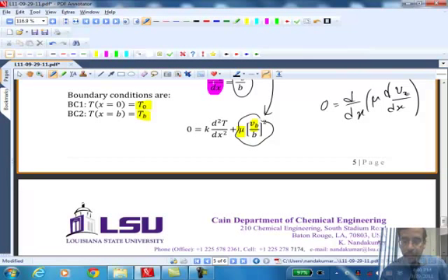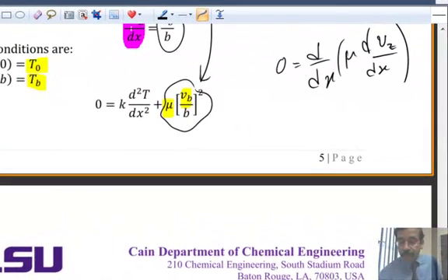temperature, but the temperature does not affect the velocity. Do you understand the idea? This is an assumption you made, an assumption about the nature of viscosity. If the temperature change is not significant, that depends on the difference between Tb and T0. If that difference is small, meaning you are maintaining a small temperature difference, then it may be reasonable to assume that the viscosity is constant over that range. Tb is larger than T0. That you control, because these are boundary conditions. You can maintain it by putting an ice pack on the inside or the outside. You can maintain it at whatever temperature you want.